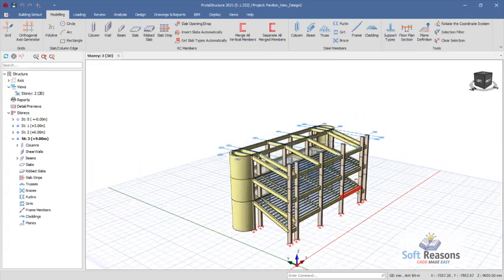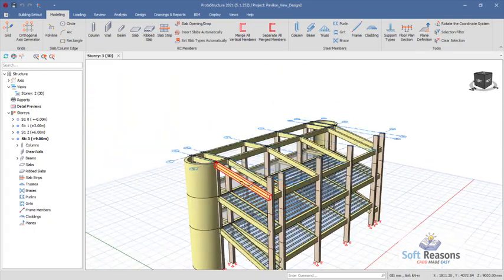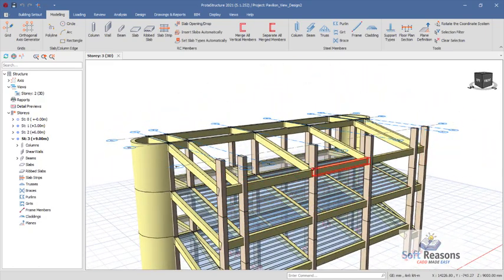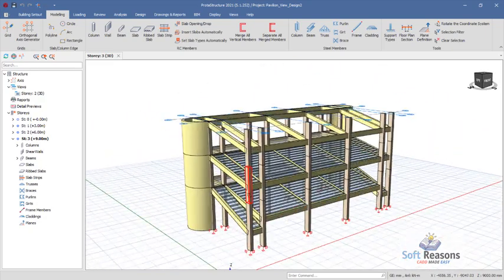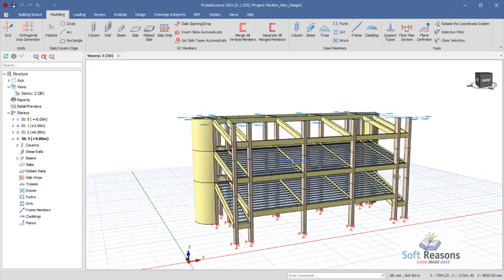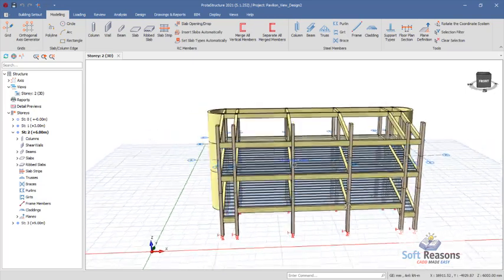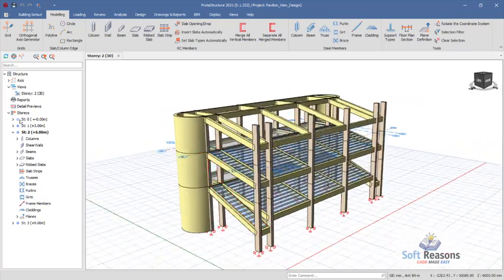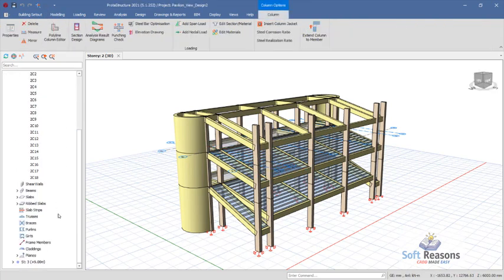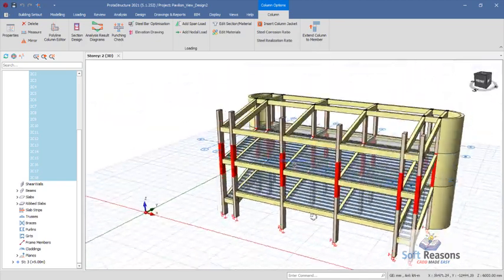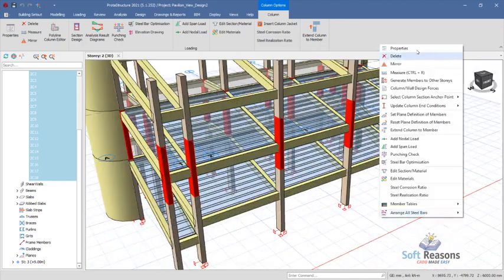All right, so what we just have to do is to remove the constraint, the plane definition constraint on these roof beams successfully. All right, but at first there's something that I would like us to do at the second floor. So navigate to the second floor. We need to change these column sections so as to fight against story drift check successfully. So we get that selected, expand the columns, select the first one, or the shift key, and select the last reinforced concrete column at that level, so you have something of this kind. Okay, so right click and then click on the property.